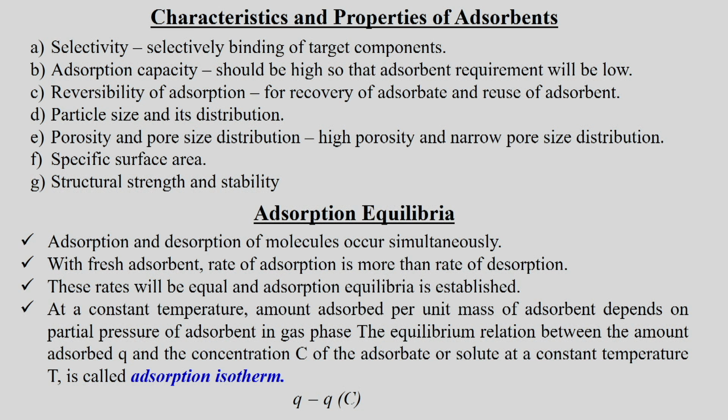The characteristics and properties of adsorbents are: selectivity, then adsorption capacity, then reversibility, then particle size and its distribution, then porosity and pore size distribution, then specific surface area, structural strength, and stability also.